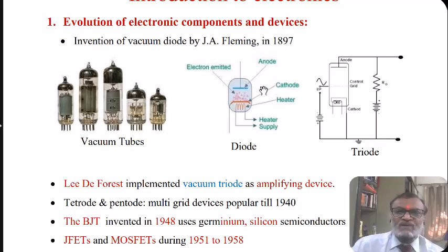Whereas when the third electrode, the grid, is added, it's called the control grid. Normally it is kept at negative potential. This negative potential intensity will decide how many electrons will be transferred from cathode to anode, and hence the flow of current. The larger the negative potential at the grid, the smaller the current flowing from cathode to anode. Thus, the conventional current is flowing from anode to cathode, right?